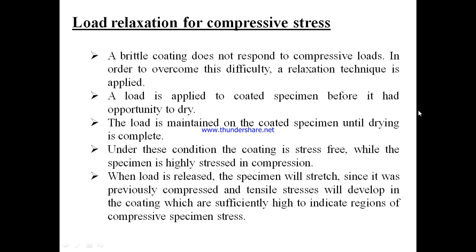We move on to the next topic, that is load relaxation for compressive stresses. Metal coating does not respond to compressive loads. In order to overcome this difficulty, a relaxation technique is applied. First of all, a load is applied to a coated specimen before it has the opportunity to dry. The load is maintained on the coated specimen until drying is complete. Under this condition, the coating is stress-free.